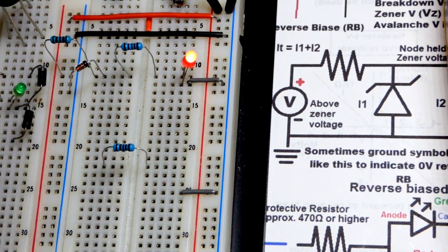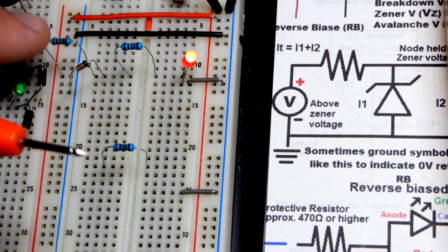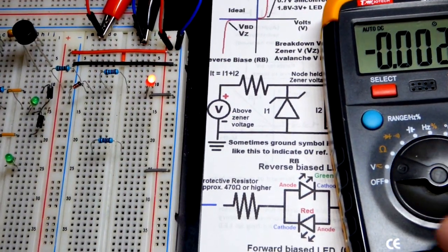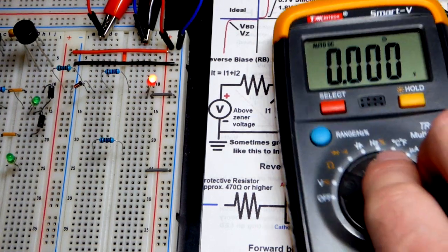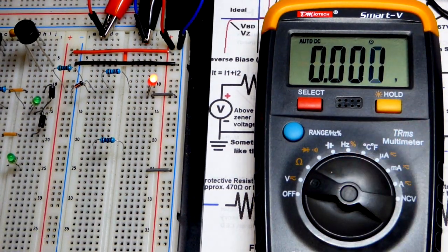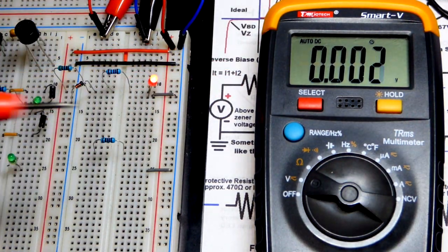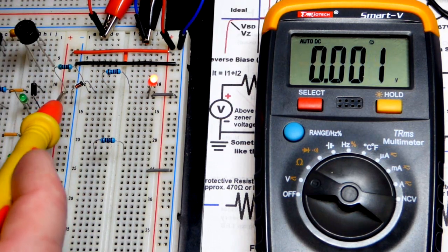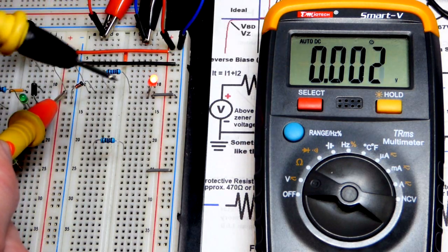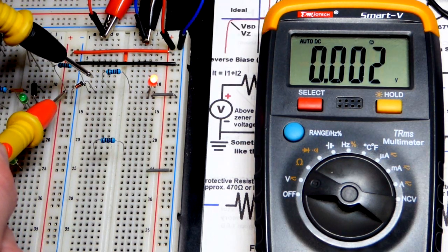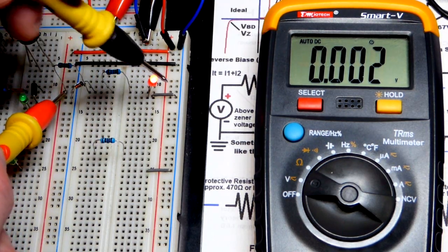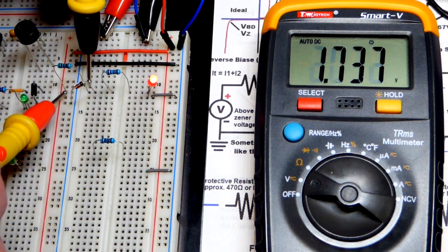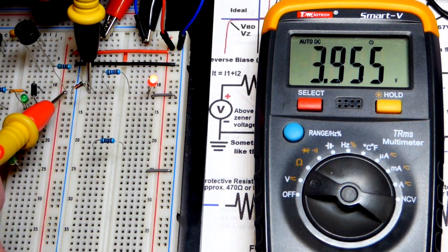And then the rest of the voltage. So this is a 510 ohm resistor because I didn't know how high a voltage I was going to go. But we have to be careful when we design this. I didn't put values on here. And so we can look at the voltage across the resistor, which should be 4 volts. Because we got the 5 volts there going that way, 5 volts going that way. The rest of the 9 volts should be across this resistor right there. And so we got 4 volts.